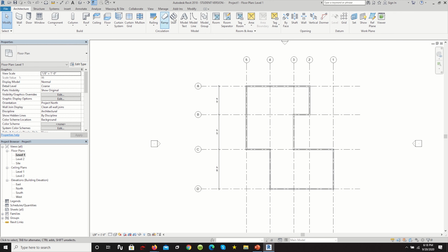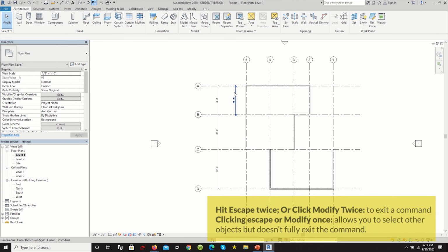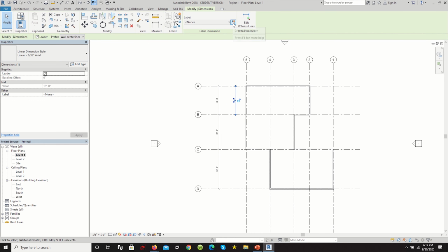So what I would do is go on the Align Dimension tool, click here, hit escape twice on our keyboard to get out of a command. And now we're going to click our parameter, and what we're going to go on is here under this green modified tab. While this is selected, you're going to see something called label. Labeling is so important in Revit because it allows you to create parameters. A parameter is a special set of requirements for whatever category you're looking into.